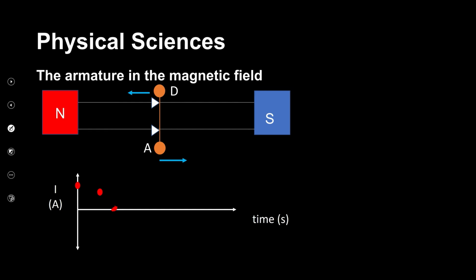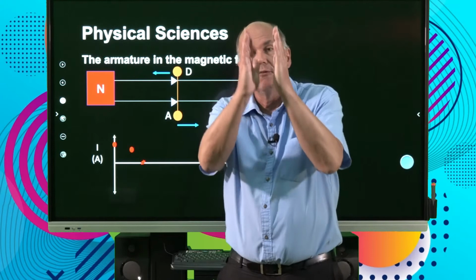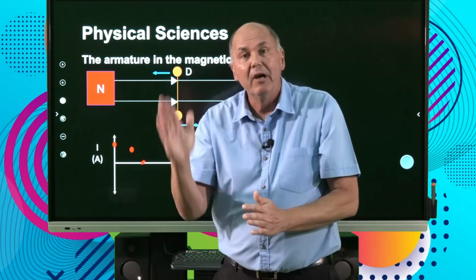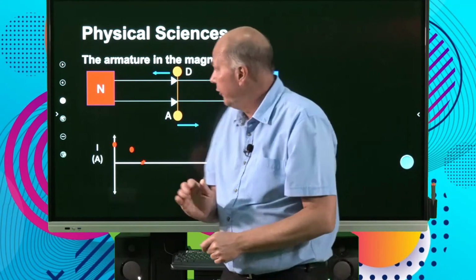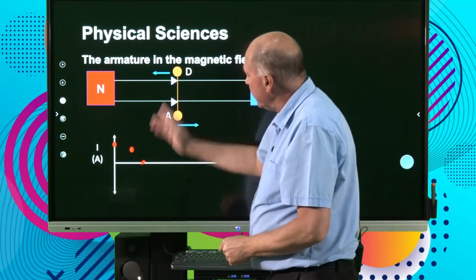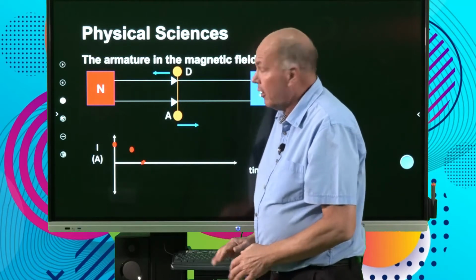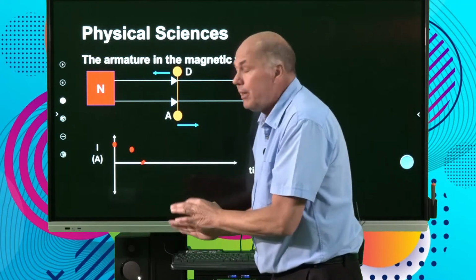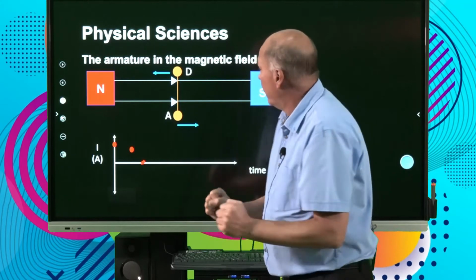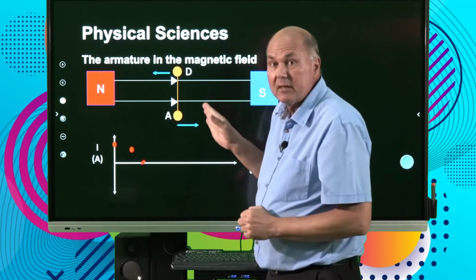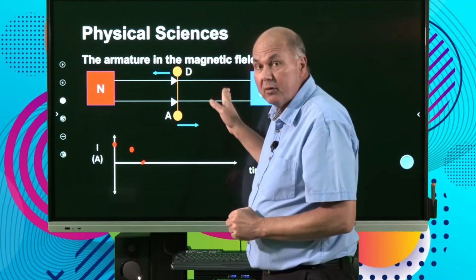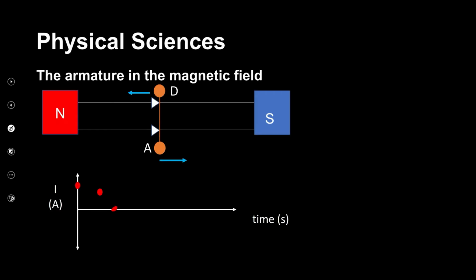So what is very important for you to see is the position of the armature in relation to the value on the graph. So when it's a vertical reading, it's going to be at 0. When it was the horizontal reading, it's a maximum. But notice in this point, these have all been positive values. Remember that D was where the current was going into the board, and A was where the current was coming out. In our next slide, we're going to see exactly what happens next.